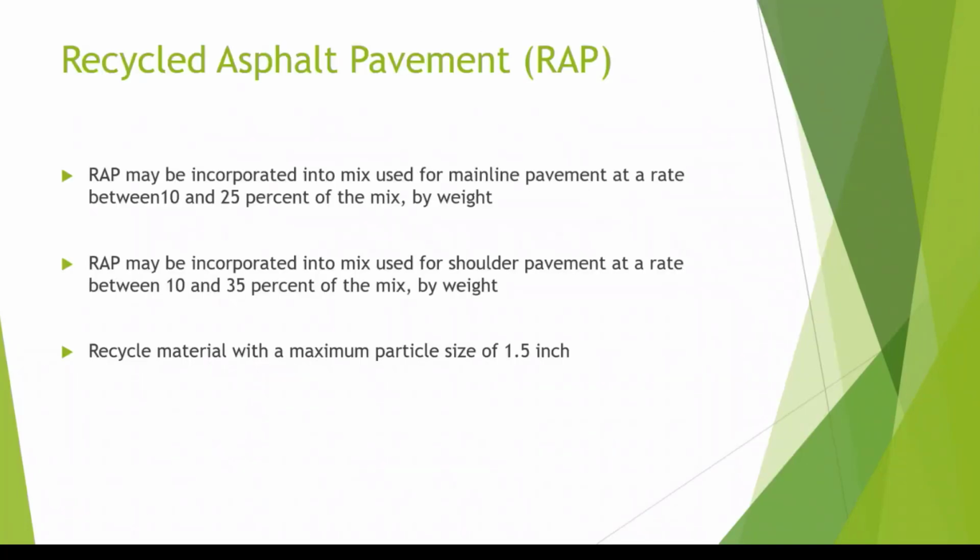So RAP, there's a lot of work going on. This is the standard verbiage in Section 430, the standard spec. Rather than mentioning anything now, probably the bottom line there is, and this has been in for a long time, recycled material shall have a maximum particle size of 1.5 inches. So obviously that's coming off your milling stream.